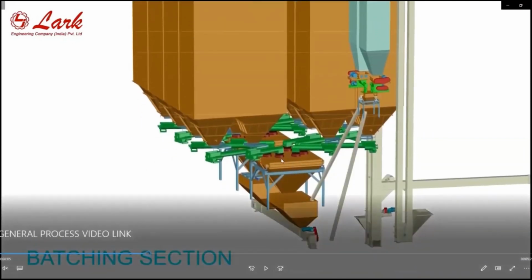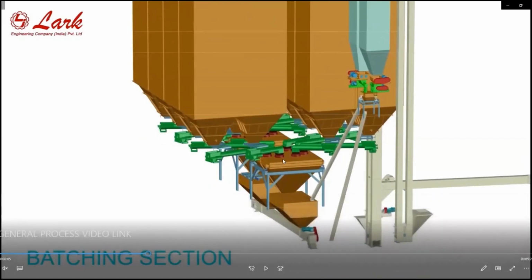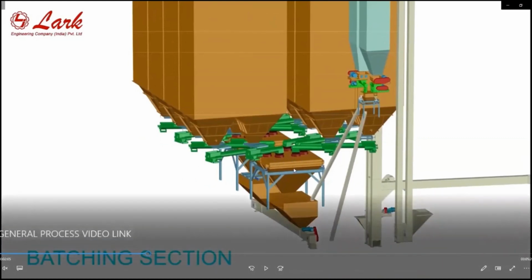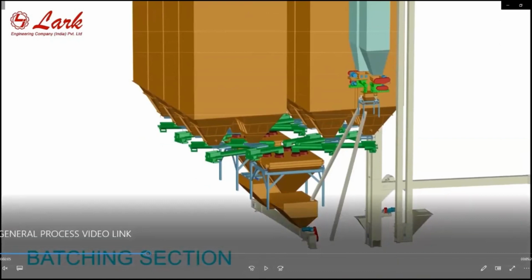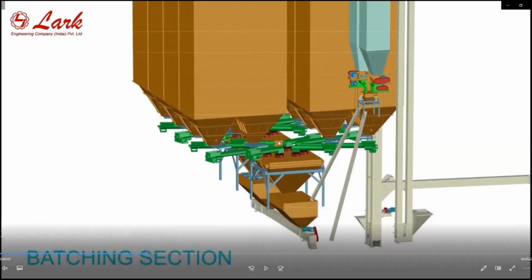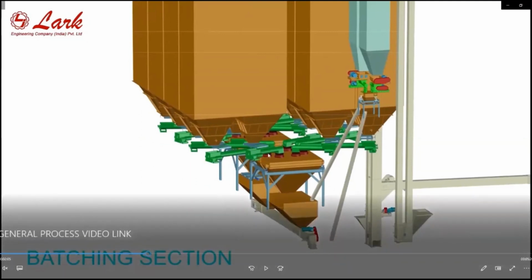These are the weigh hoppers, and below the weigh hoppers there are dump hoppers. To save time and enhance capacity, when the batch completes, the gate opens all at once and the batch dumps to this dump hopper, and these weigh hoppers are ready for the next batching process. For free flowing materials and grains, we generally use gravity feeders. For fibrous material and material with less flowability, we use these screw feeders.